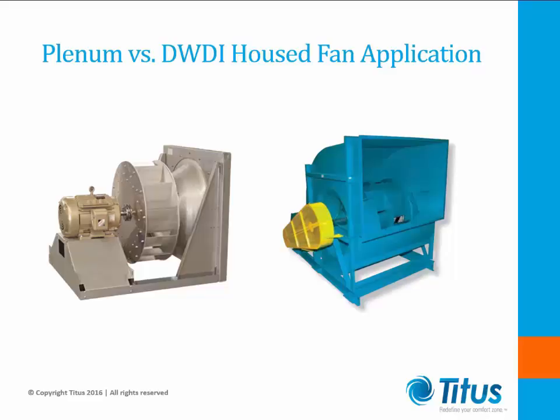When it comes to mechanical space optimization, a housed double-wide fan requires a straight run of duct per AMCA guidelines at the outlet of the fan before elbows can be applied. This constraint imposes restrictions on duct layout and mechanical space design, which generally increases overall footprint requirements. The ducted takeoffs from pressurized plenums, as in the case of the plenum fans, do not have a requirement for a straight run and afford greater flexibility to the architect or engineer in ductwork design.